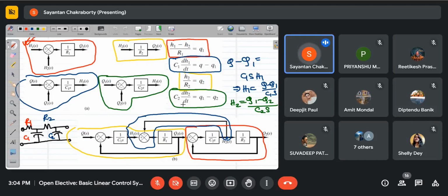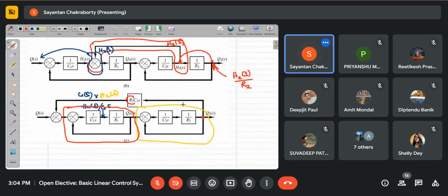And the third method is that you obtain the equations in the Laplace domain, say from first principles, and then represent the Laplace domain equations in terms of sub-block diagrams, and then you combine all these block diagrams to arrive at the final block diagram, and then apply the rules of block diagram algebra to finally arrive at the solution.